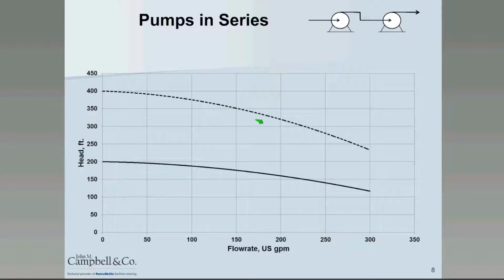This new pump curve drops steeply, which means that as your system curve increases on here, you have a sudden drop in performance. Let me illustrate that by drawing onto here the system curve. So here's our system curve that we'd considered previously, and we expected our operation at about 200 GPM. Now when we increase capacity, we run two pumps in series, we see an increase in capacity to around about 280 GPM. That's about a 40% increase in capacity for running two pumps.